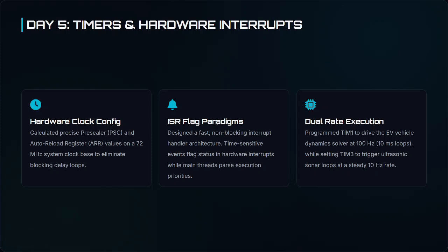After that, we designed a non-blocking interrupt hardware architecture and programmed Timer 1 to drive the EV vehicle dynamics solver at 100 Hz, that is a 10 millisecond loop, while setting Timer 3 to trigger ultrasonic loops at a steady 10 Hz rate.